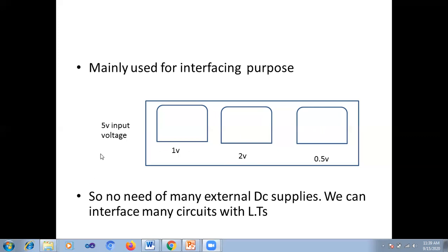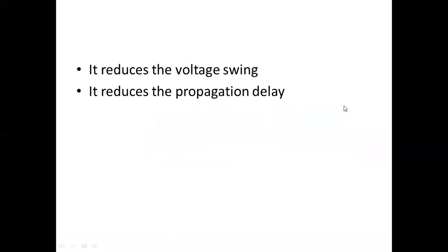So for this conversion also we will require the level shifting circuit. Mainly for interfacing purposes, this kind of level shifting circuit is required. In many situations we will require many external DC supplies, so we can interface many of the circuits with the help of level shifting circuits.